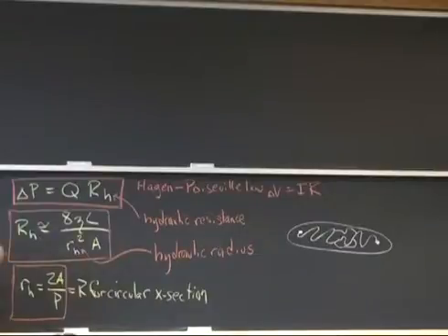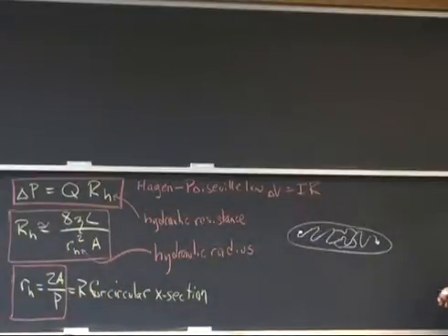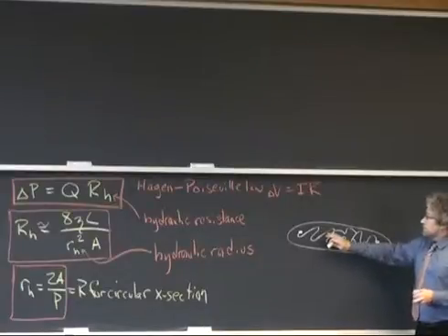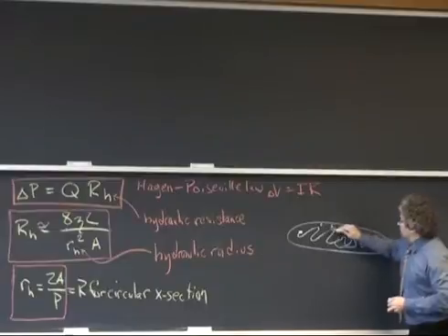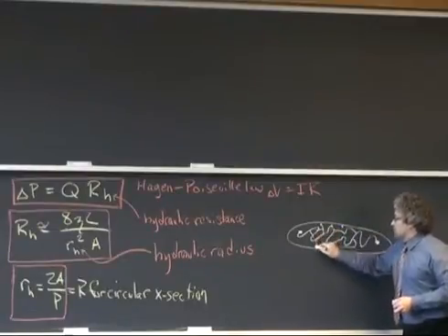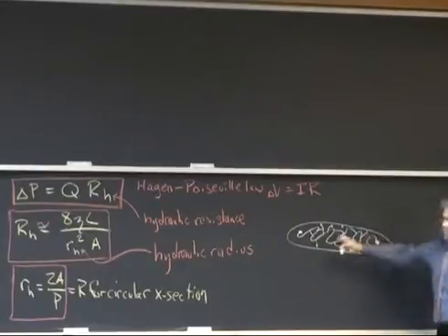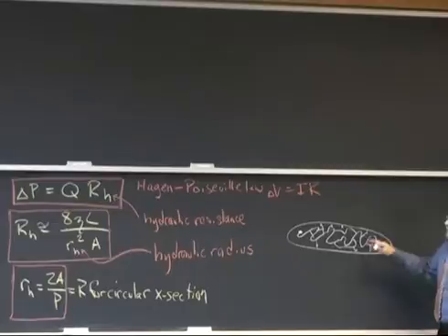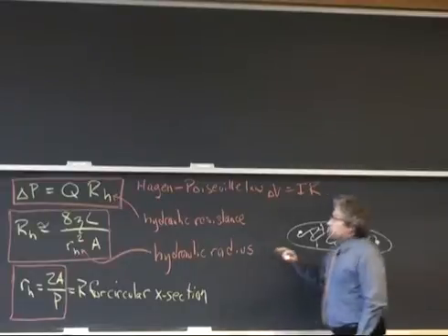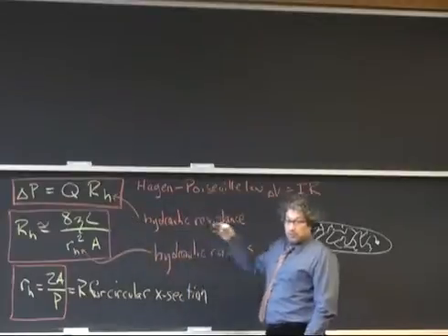And because this is all a linear system, it doesn't require my solving any ordinary differential equations or partial differential equations. This allows me to take a system like this, and even if I make it much more complicated with lots of inlets and outlets and connections and different sizes and shapes and different depths, no matter how complicated I make this device, I can still come up with a solution quite straightforwardly because it's basically a bunch of linear equations. I can just put it in a matrix and invert it.